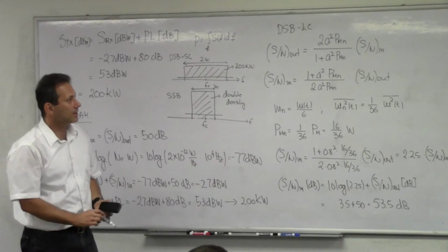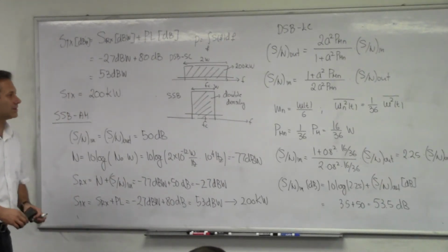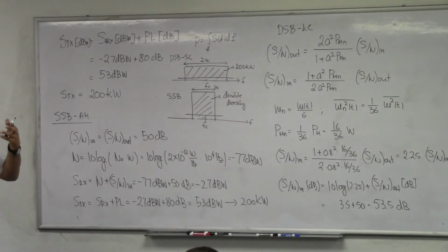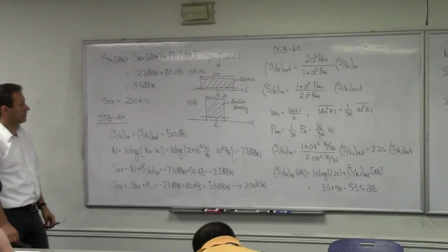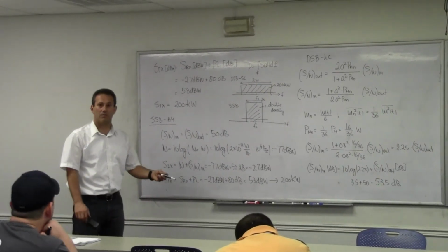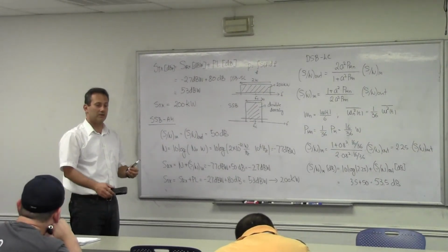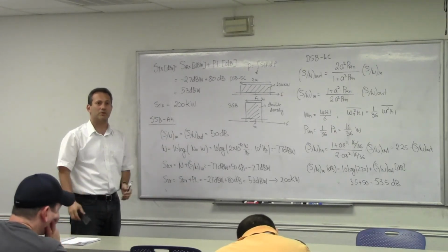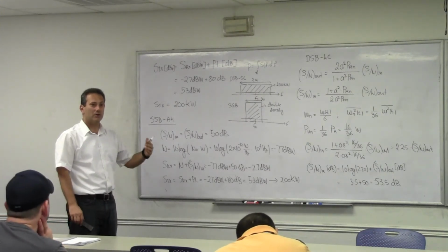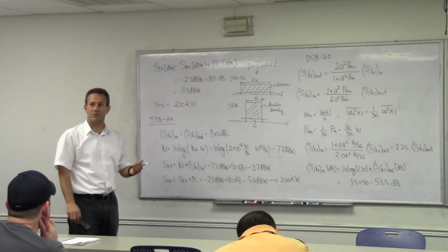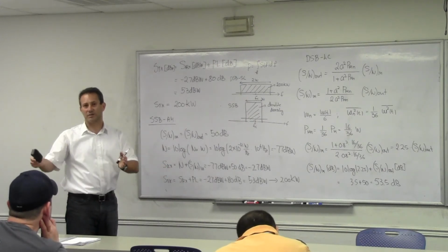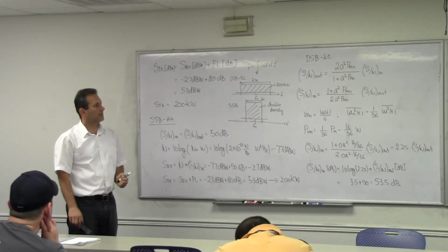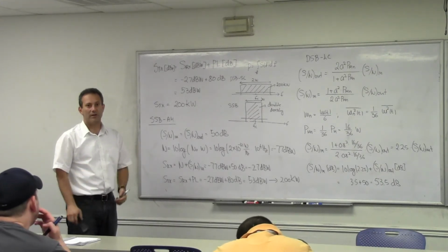All right. So we're done with analog. These were relatively easy, but it's very nice in terms of understanding what is actually happening here. We need to do the same task now for FM modulation. And just like we had problems in determining what is the spectral footprint of the FM modulation signal, here we're going to have the same kind of challenges because FM modulation is not a simple translation of the spectrum from baseband to the passband. It's quite non-linear in nature.